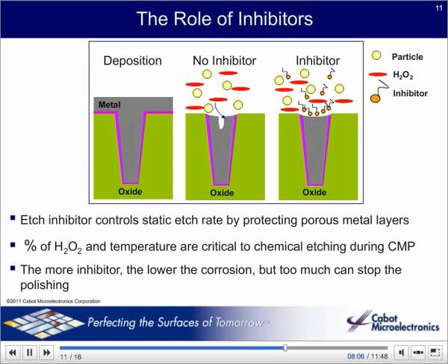Many metals are extremely susceptible to acid pitting corrosion, especially at knit lines where the metal deposition process grows from the edges in and joins in the center. If there are voids in the structure or just poor microstructure, this can create what we call a keyhole defect, as we will see in the next image.